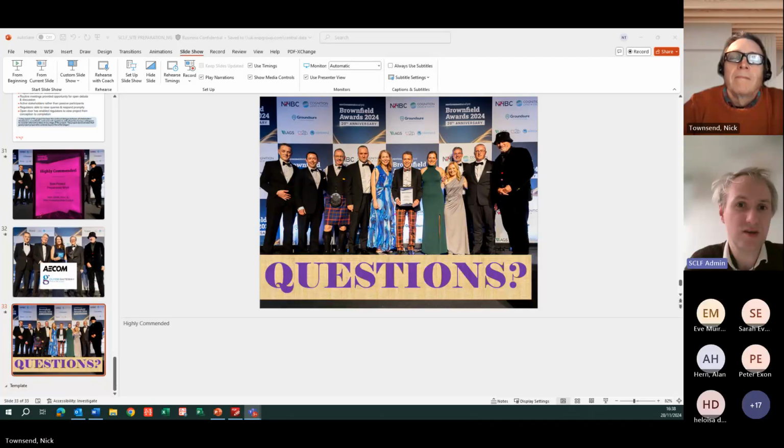I think for the nature of the soils that we had, through doing their testing, DEME were able to demonstrate that it was predominantly the granular fraction that was impacted. That was the majority of materials. So soil washing made sense in that effect. I also think what hadn't been taken into account when thermal was chosen was how you'd actually put the treated materials back down, because they'd needed some degree of treatment in order to reuse. As I said, I think the client was very relieved that they did switch to soil washing given the price hikes in gas.